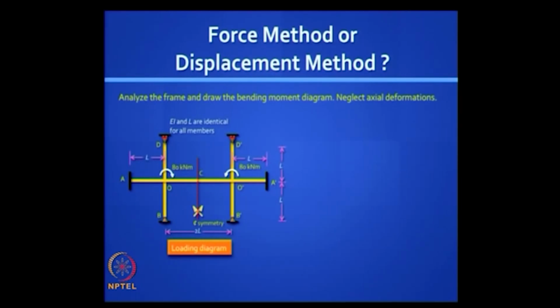How long would it take you to solve this by the force method that you know? Okay. The indeterminacy is more. How much is it? But here it is only 1. Okay, first let us take advantage of symmetry, right. So let us cut the beam at the center at C. The appropriate boundary condition is a guided roller support, because rotation there is 0 but it can deflect.